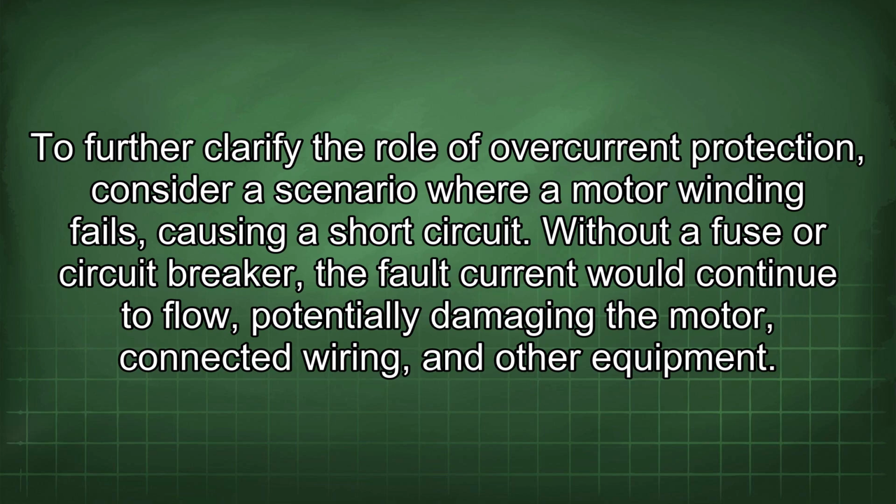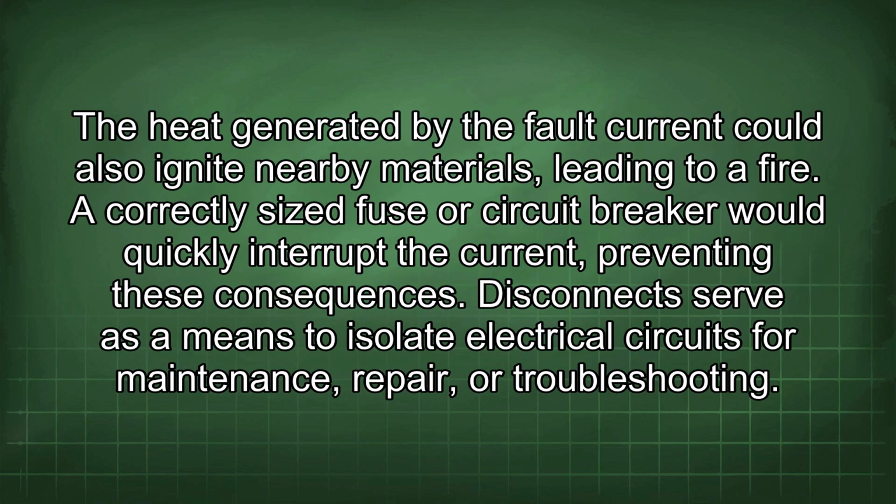To further clarify the role of overcurrent protection, consider a scenario where a motor winding fails, causing a short circuit. Without a fuse or circuit breaker, the fault current would continue to flow, potentially damaging the motor, connected wiring, and other equipment. The heat generated by the fault current could also ignite nearby materials, leading to a fire. A correctly sized fuse or circuit breaker would quickly interrupt the current, preventing these consequences.